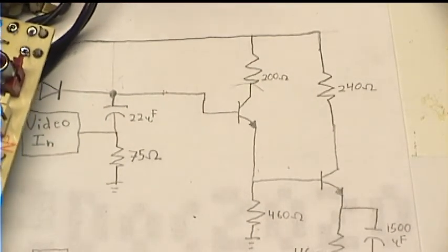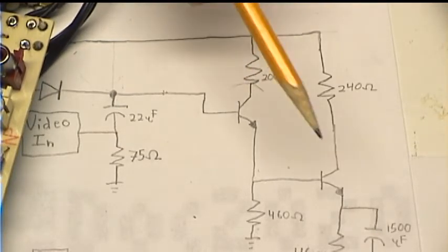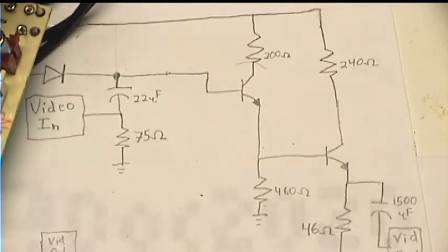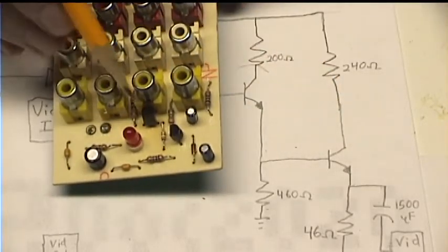Now, you notice there are also some resistors here I didn't talk about. These resistors on the collectors of the transistors, I guess they're just there to provide some current limiting to prevent excessive current from going into the transistors. And it also evens out some of the thermal dissipation, so not all of the heat goes into the transistors. Although this larger final transistor does get rather warm.